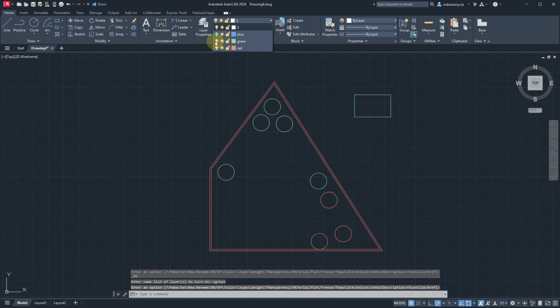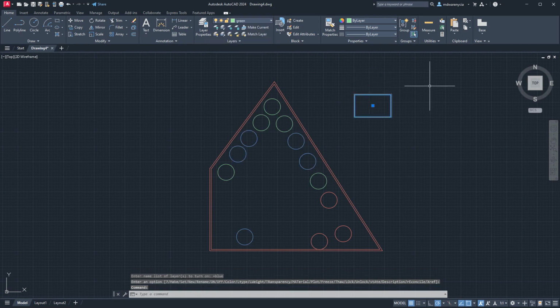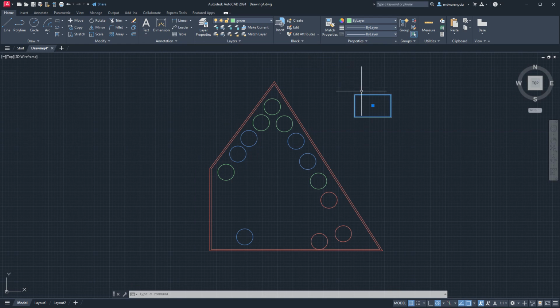Oh no, it didn't do it. Anyway, I've seen cases where something has been assigned to two different layers, I think it's a block issue. Something is drawn on one layer, and then moved to another layer, and if either of those two layers is turned off, it disappears. So someone would turn off their windows and their furniture would disappear.